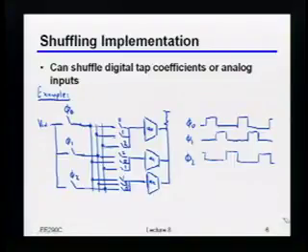So there are even things people did where they would have a bidirectional system where in the forward direction it's your nice clean differential link, and the reverse direction, whose only job was to tell the transmitter what its equalization was supposed to be, was done on the common mode of that differential link. So it's just a matter of being clever to get the information you'd like to send back to the transmitter. But that can actually be trickier than you may first think. Does that make sense? Yeah. Okay, great.